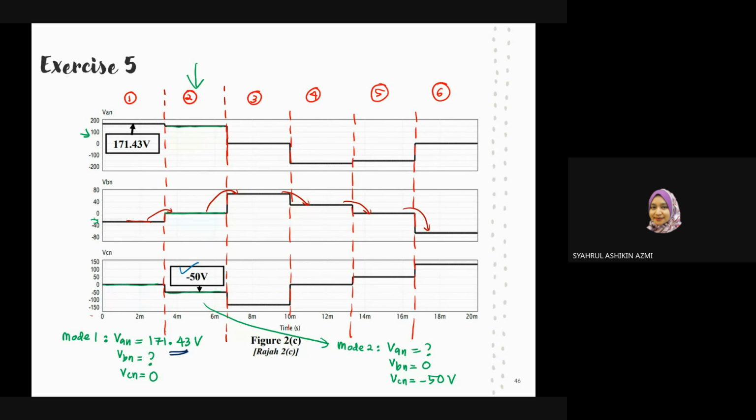Look at here. Before that, the x-axis is from 0 to 20 millisecond, where 20 millisecond is 360 degrees, which is 2 pi. 10 millisecond is pi, or 180. Now once you have drawn the dotted lines, next identify what information has been given in this figure.